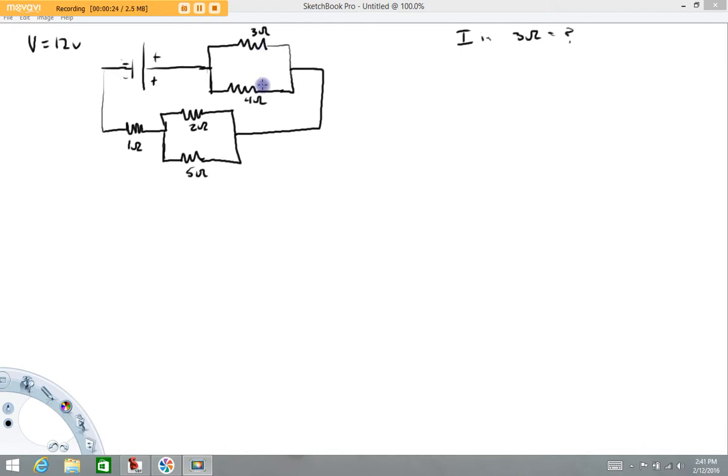I'm going to go ahead and draw currents now. There is going to be a current in this branch right here, and I'm going to call that current I1. The direction is dictated by the battery voltage. Remember, current always goes from plus to minus, assuming positive charge carriers. At this point, there's going to be some divvying, so we're going to have currents here and here. I'm going to call that one I2, and the current in this branch, I3.